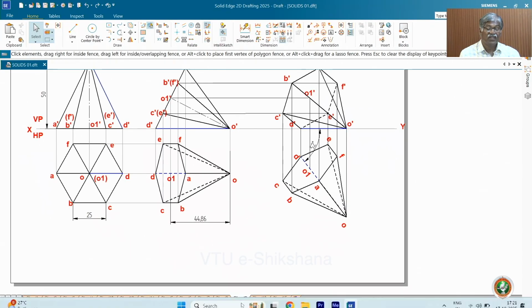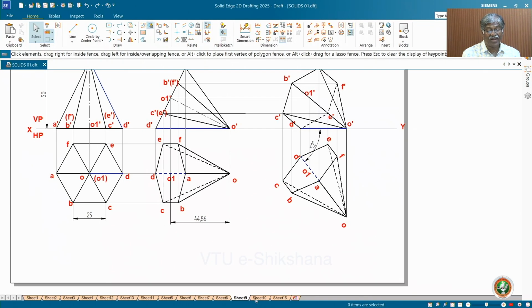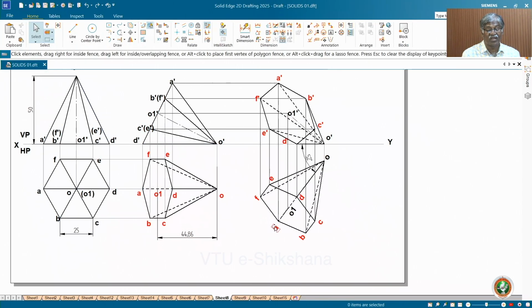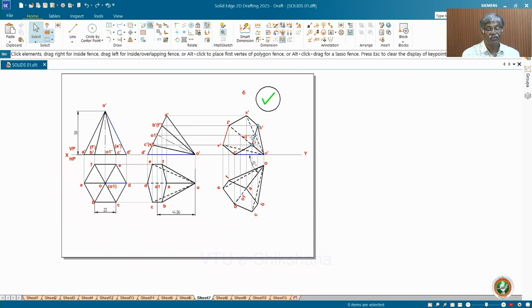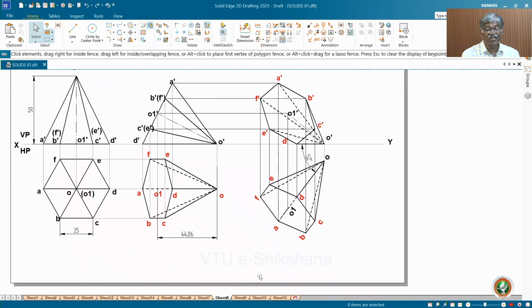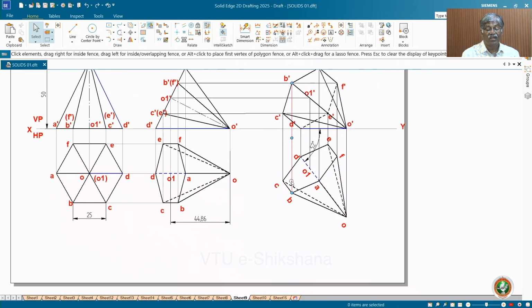Okay, now, in the previous case I had the base towards the observer, and got the base visible. Now, in this case, the base is away from the observer. Definitely the base is not visible. Boundary is dark, invisible surface edges other than boundary lines are dotted, invisible surface, visible lines, all opposite. So whatever you had previously becomes the opposite, except boundary lines.